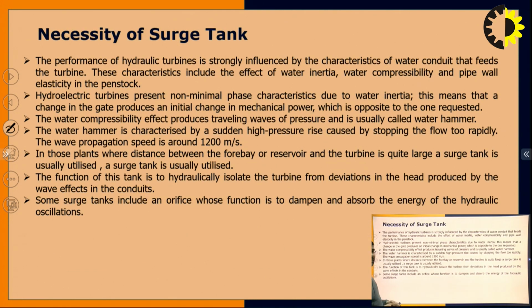So, what is the necessity of the surge tank? The performance of a hydraulic turbine is strongly influenced by the characteristics of the water conduit that feeds the turbine. These characteristics include the effect of water inertia, water compressibility, and the elasticity of the pipe wall in the penstock.